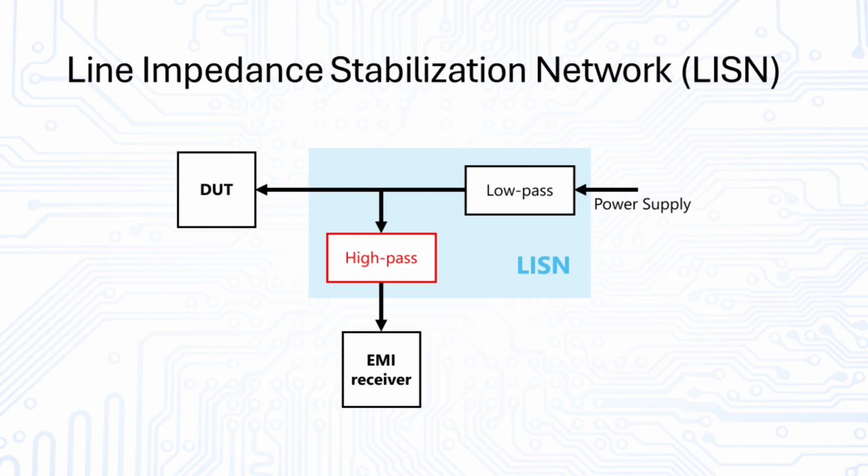Thus, together with the low-pass filter, which blocks the high-frequency components from the DUT, as well as potential noise signals coming from the power supply, we only receive the desired high-frequency conducted emissions on our measurement instrument. This ensures an unaltered measurement of the conducted emissions for different measurement setups. The blue and red arrow indicate the paths taken by the supply signal and high-frequency signal, respectively.